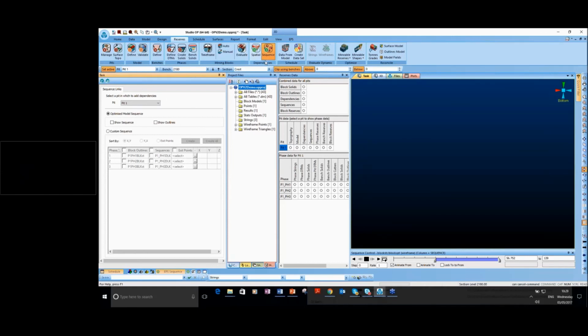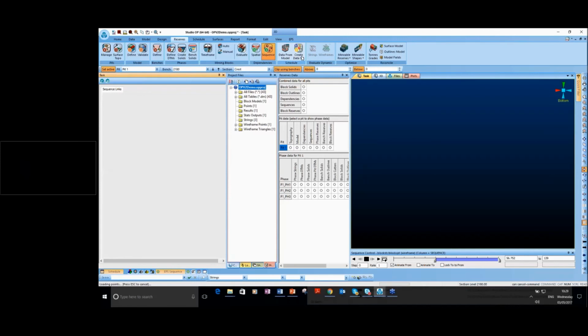After we finish the sequence, the next step is to create the dataset. Why are we doing that? In some scenarios, a user wants to create different mining blocks with different sizes, and then we want to try it in the next step, which is the schedule. So after I finish the job, then I can go to create dataset, and then I can create a new dataset.